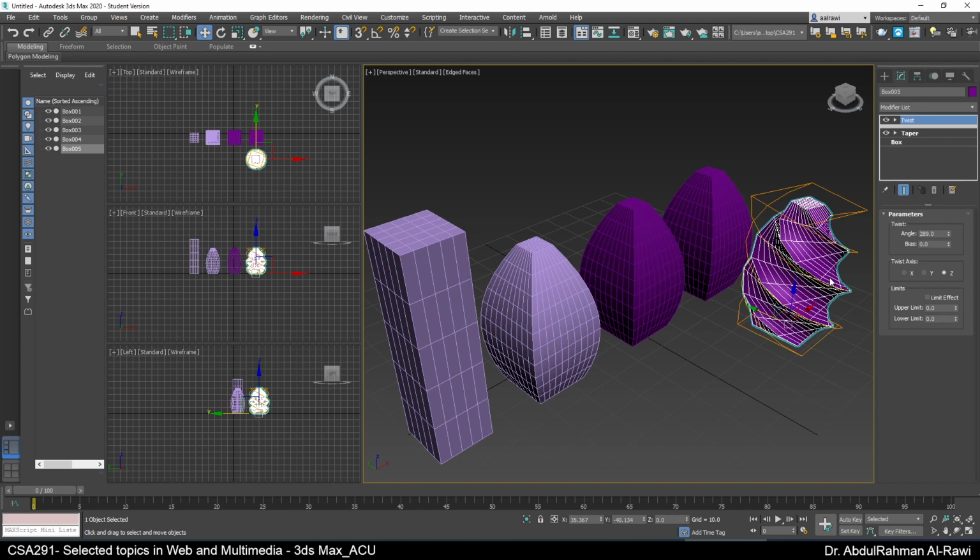And the best way to make sure that you understand all of them after you see the recording is, just like I did, to go and try them yourself. Do a normal copy, and then do an instance and try changing the object values and the object modifier parameters, and then go and check the reference as well. So you have three types of cloning in 3D Studio Max. The first one is the copy, normal copy, and then instance, and then reference.